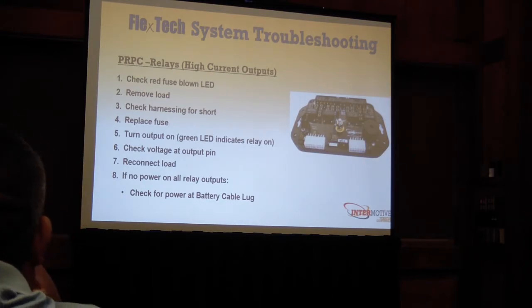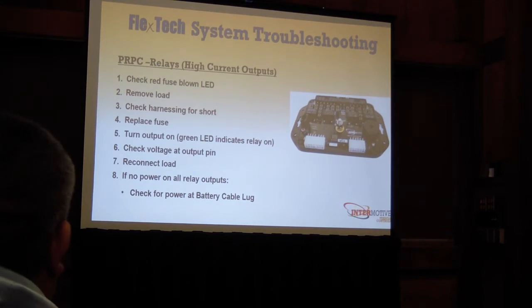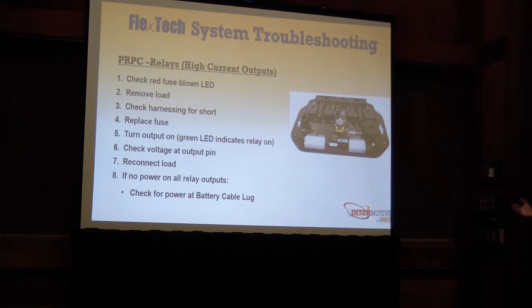The main purpose of these outputs, you're getting vehicle data and allowing the designer to write these logic equations with inputs, vehicle data, output status, complex logic with very simple wiring, right? So you don't have to go and get all these different vehicle signals, relay logic.